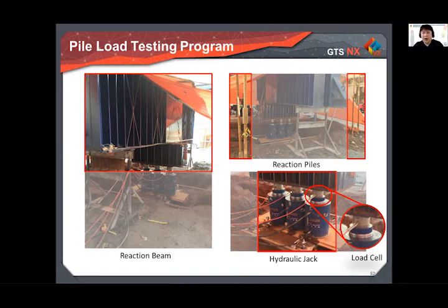The geotechnical design starts with the design of the pile load test. So we define the type of pile, the diameter, the length, the maximum test load, and also the reaction system. We followed up the execution of the test and later interpreted the results.